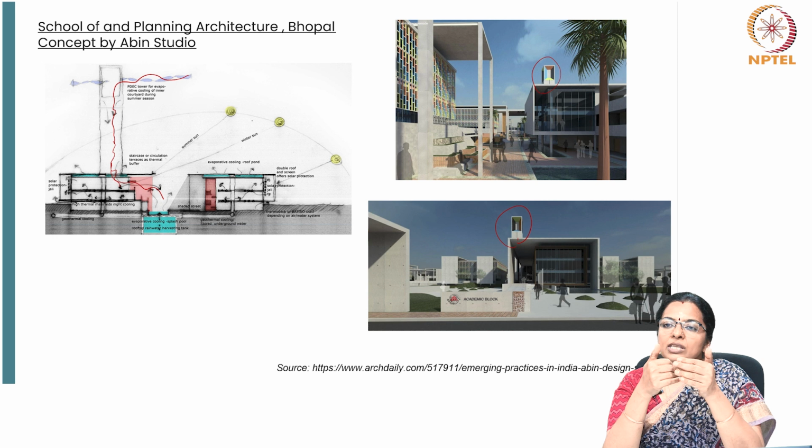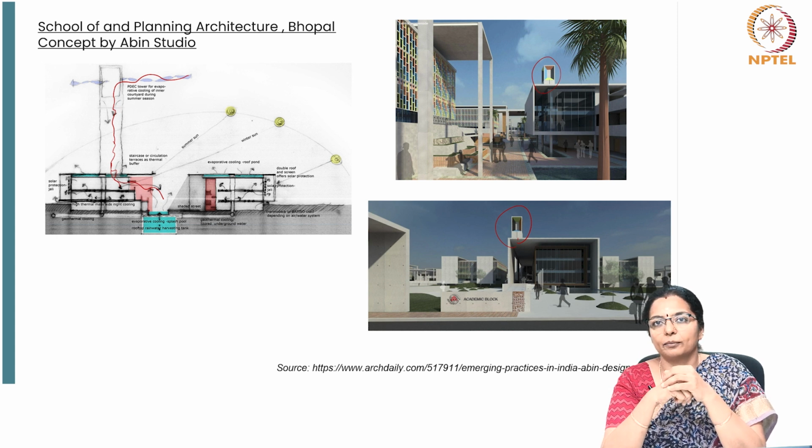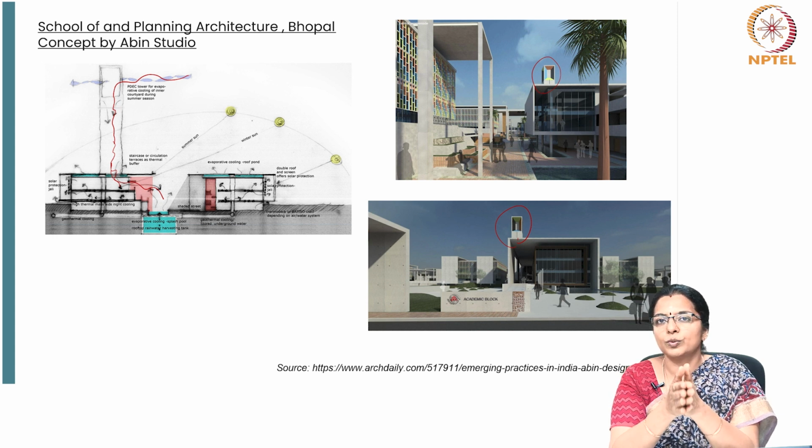That is because this system involves the use of a water body in order to cool the air, in order to make the dry air humid, and in that process cool the air. Air which is already humid will not function effectively using this technique. How this technique gets translated in architecture is left to the individual designer.